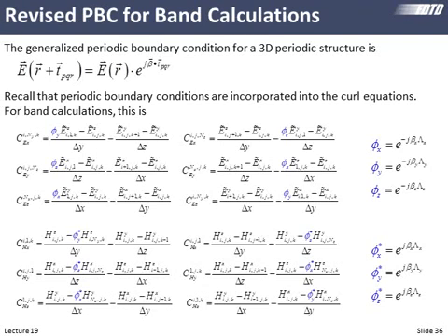Now here, this is very similar to the sine-cosine method, but we're exploiting the benefit that MATLAB can incorporate complex numbers. So we have a periodic boundary condition here, and we incorporate it into Maxwell's equations this way. It goes into the curl equations. We calculate these phase terms, which is the phase across the grid. This is a complex quantity. And these are just the equations, the curl computations at boundaries where corrections are required. You notice we're incorporating these phase terms in here. So suddenly our electric field values become complex. And that's okay. We're really doing a sine-cosine type of method.